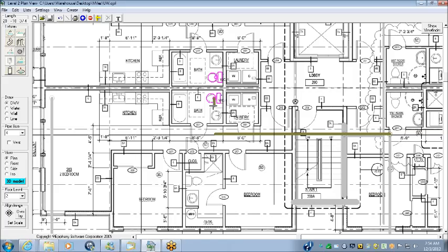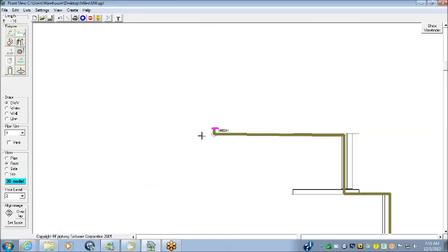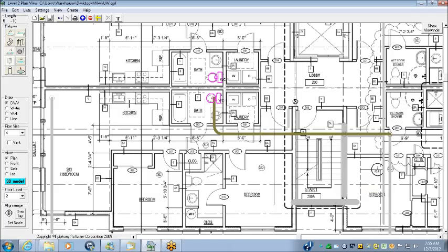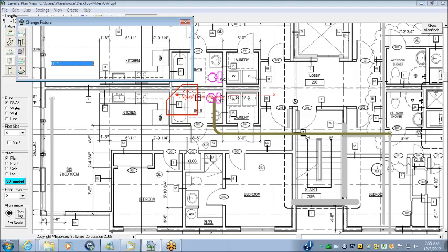Now, we got room there. It didn't take because we didn't have quite enough distance between the toilet and that horizontal pipe for a quarter bend or a closet bend to fit. Now we see that we do, and we'll go ahead and finish out a bathroom.